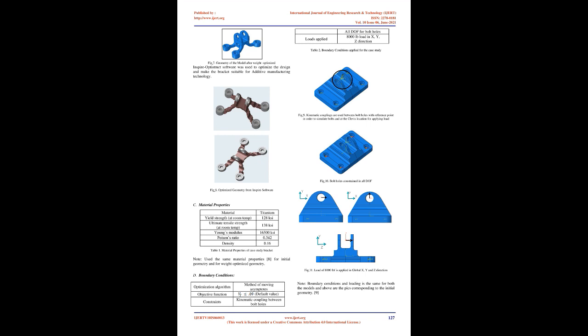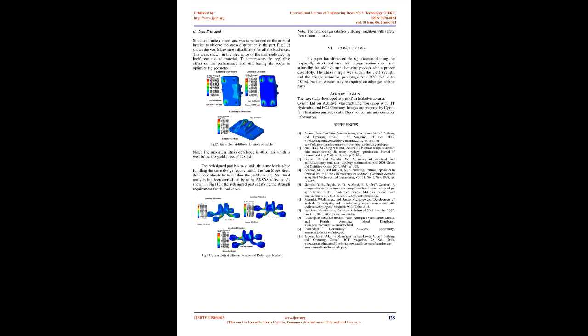Conclusions: this paper has discussed the significance of using the Inspire Optistruct software for design optimization and suitability for additive manufacturing process with a proper case study. The stress margin was within the yield strength and the weight reduction percentage was 70%, 6.8 pounds to 2.0 pounds. Further research may be required on other gas turbine parts.